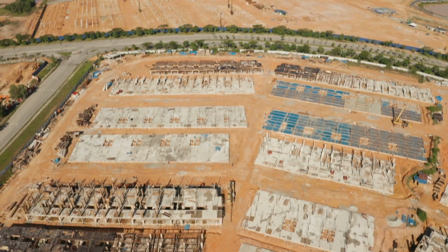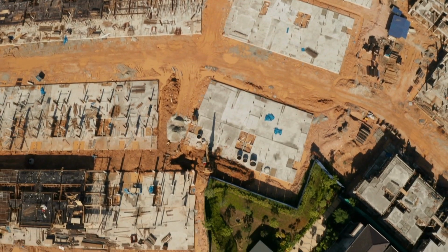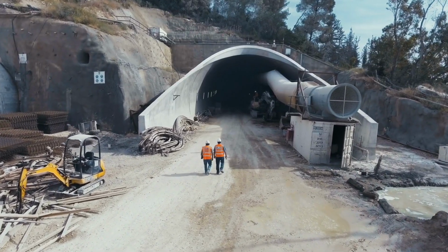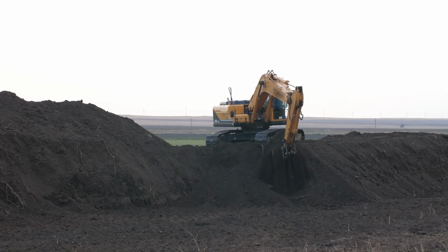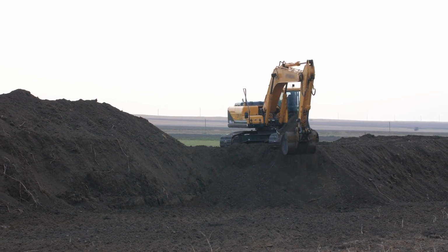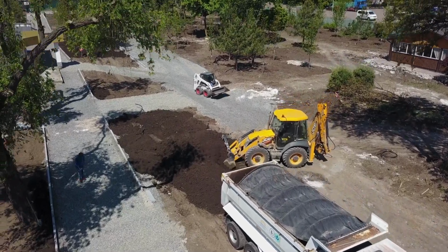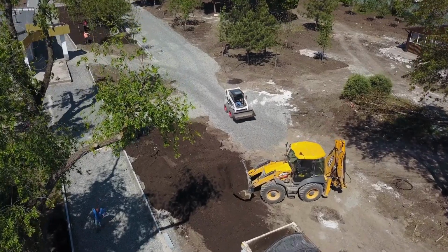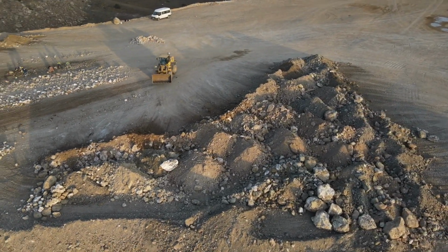Civil drawings represent the entire site of a project, rather than just a specific structure that's built on the site. Civil drawings often show roadways, drainage, sewerage, major utilities, earthwork, and other bigger picture site details that are also part of the project. And this information is often in addition to the building being built, as we said before, to account for the work that needs to take place to facilitate that construction, as well as the work that needs to happen in the surrounding area.